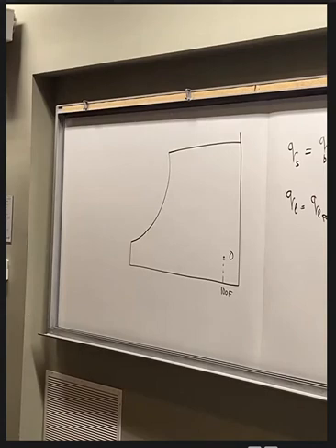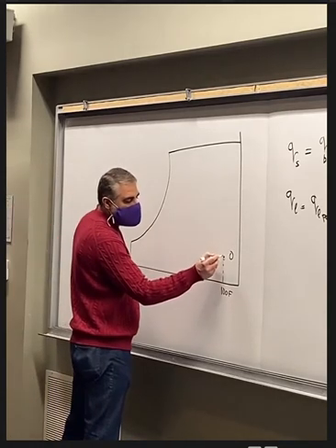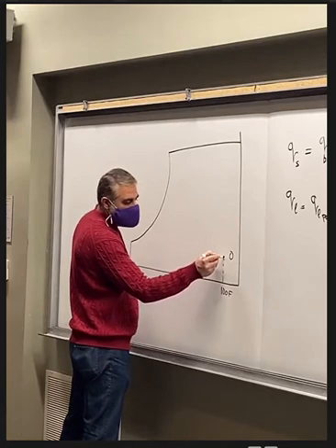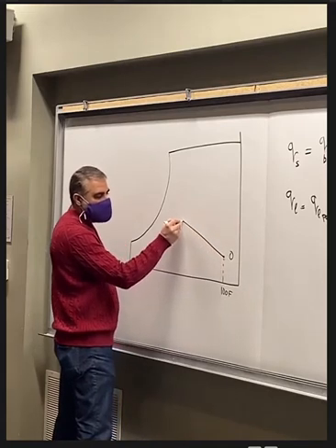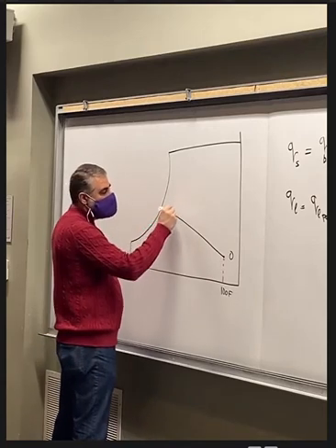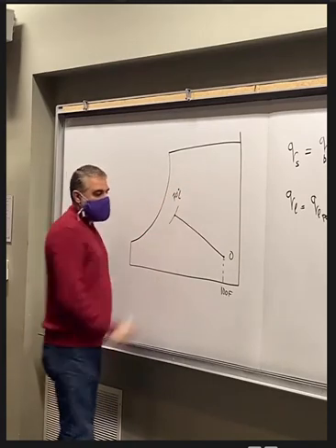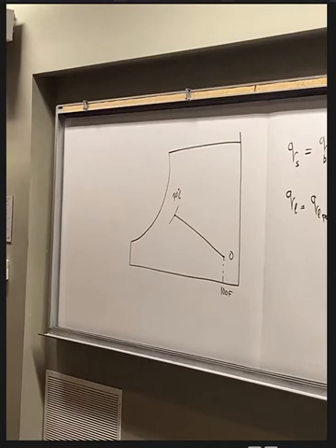So the relative humidity of the air after the adiabatic humidifier is equal to 70%. So what does that mean? We have to draw a humidification line. It will intersect with relative humidity equal to 70%. And that is point number 2.